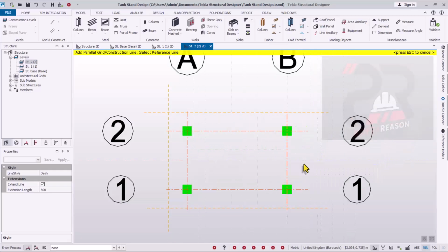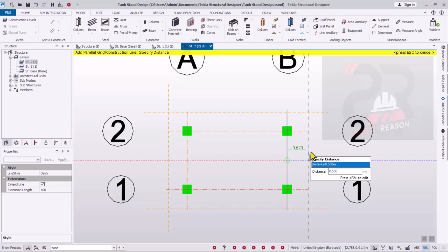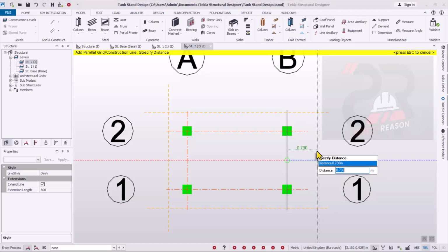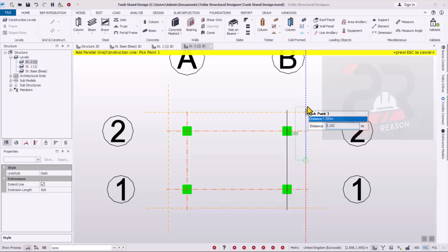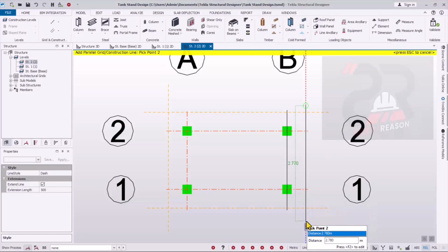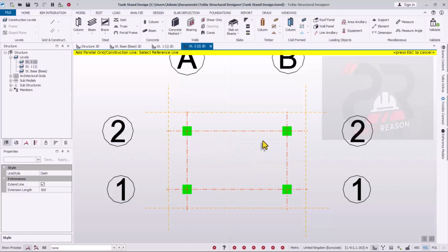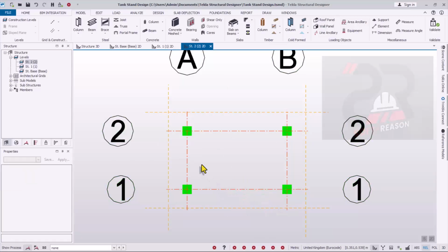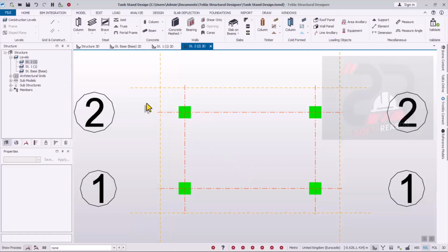Okay, I escape. I pick from these directions, move my hand this way to the right, F2 on the keyboard, 0.45, and then enter. Move your hand elsewhere right here, pick, come over to this side and pick successfully. All right, escape. Now we have set out our cantilever beams grid line successfully. So you want to start to place the beams.